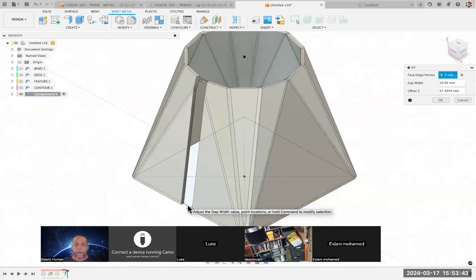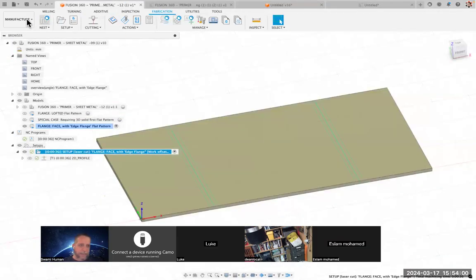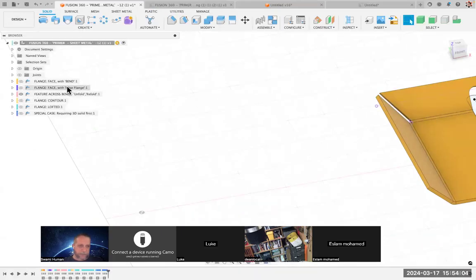So in order to deal with that, you have to make a sketch and reference the line, project in the line, find the actual midpoint and the value and use that value. So that is a little bit convoluted, but I will show what that is in here just so it might make a little more sense.